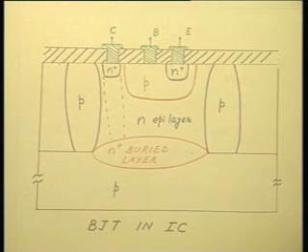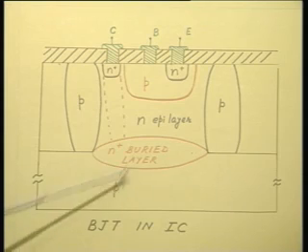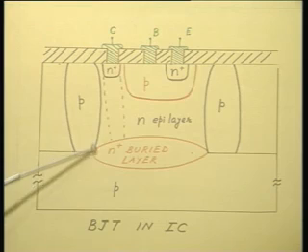We started with a p-type substrate. Normally we used 111 substrate. Remember, it is a comparatively older bipolar junction transistor. So, in those days still 111 substrate was considerably cheaper than 100 substrate, because now you know that it is much easier to grow 111 crystal, right. So, 111 substrate used to be much cheaper, that is why people started out with a 111 about 10 ohm centimeter substrate. Okay. And then you know the first step was in forming this N plus buried layer.